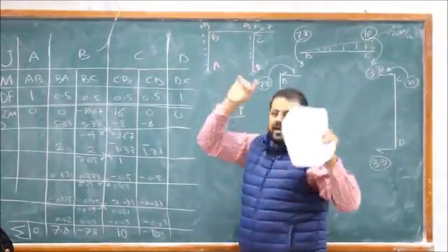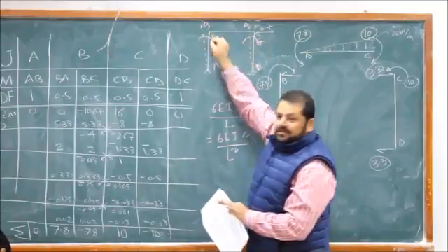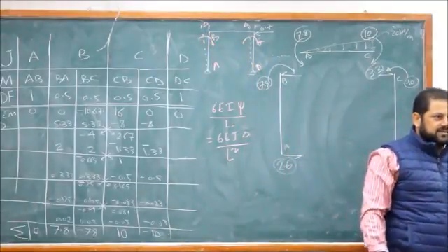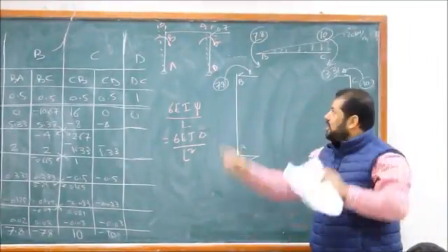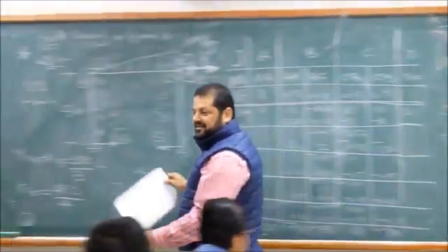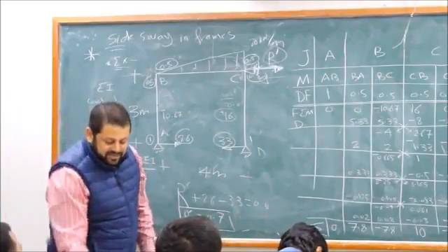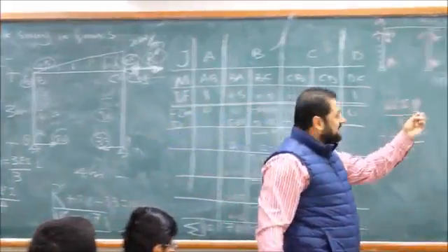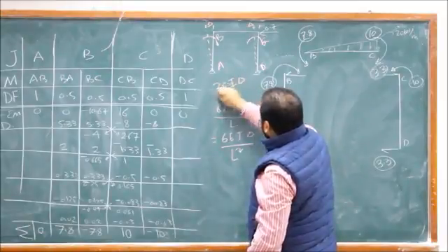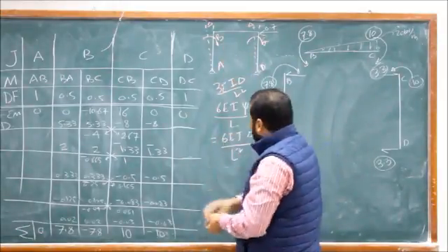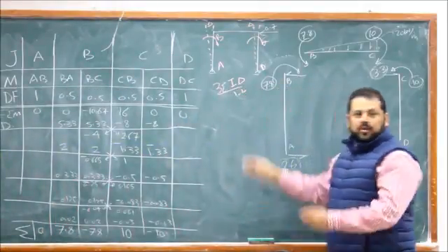So what I'm saying here is, you apply psi here. What is the fixed moment here going to be? Opposite to psi. Psi rotates this way, so the moment is opposite to psi. Good. So how much is this one? We said 6EI, sorry, 3EI delta over L squared. In this case, because you have pin and fixed, it is 3EI delta over L squared. Our case is fixed-pin, not fixed-fixed. The 6EI is for fixed-fixed. That's not the problem.